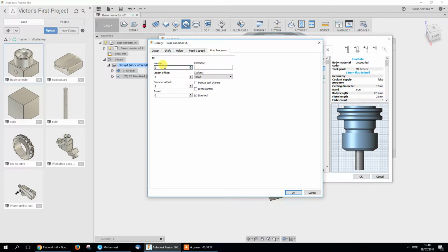And the post processor, the number, it means the position of the tool. If we're using the Haas, we have 9 positions plus the probe. We can define the position here so that the machine can go get the right tool to machine. So if we have a 12 millimeter, we'll put it on position 2 for the machine to go there and start using that tool. Okay? So because automatically you have to change the number. If you set them previously on the machine, you can come to the software and say that tool is in this position. You can go get there.